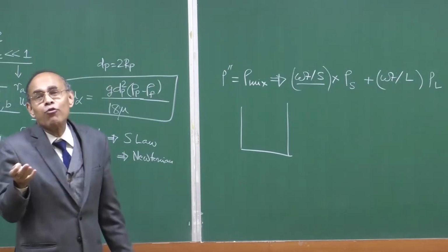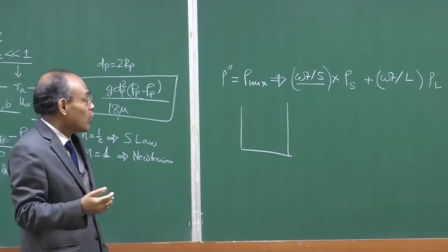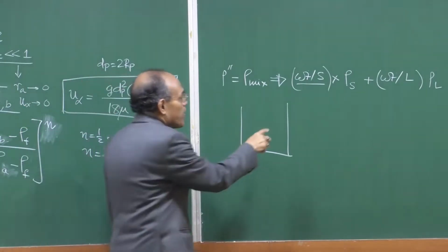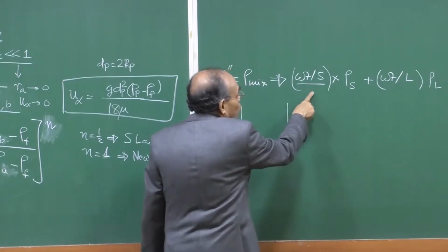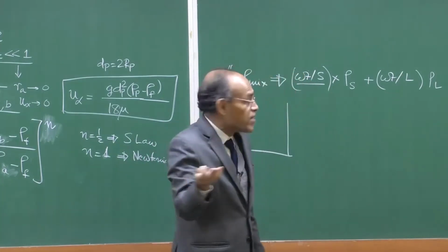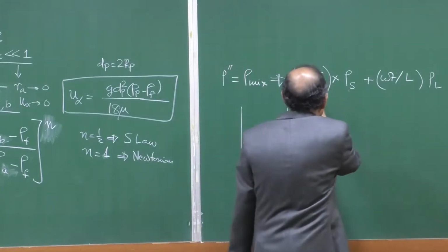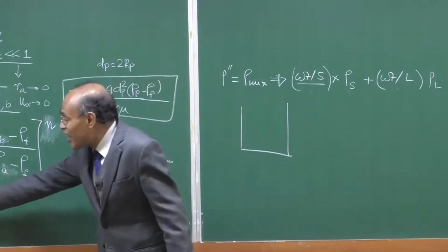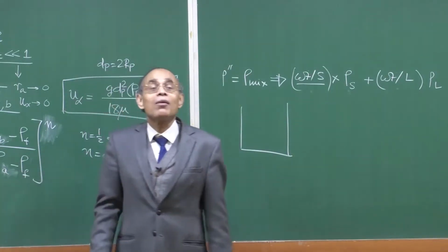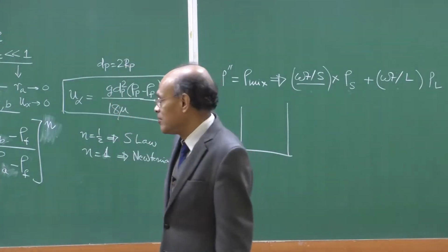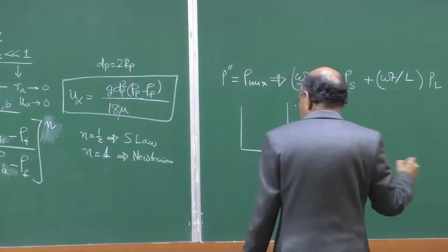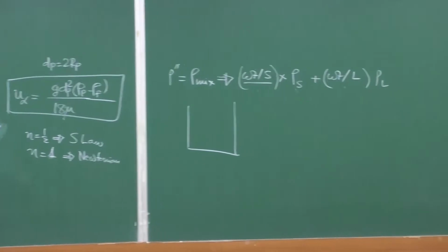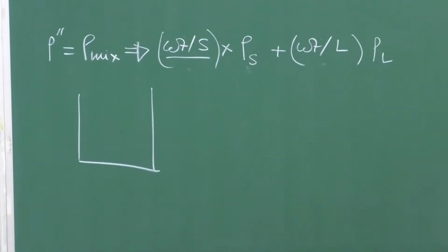So, if you have, for example, 40% by weight, of course you have to know the loading, that is called the solid loading ratio in the system. So, if you have 40%, weight percentage solid is 0.4 and weight percentage liquid is therefore 0.6. So, 0.4 into rho s plus 0.6 into rho liquid, and that is the density to be used, which is basically the rho double prime to be calculated in the context of hindered settling ratio.